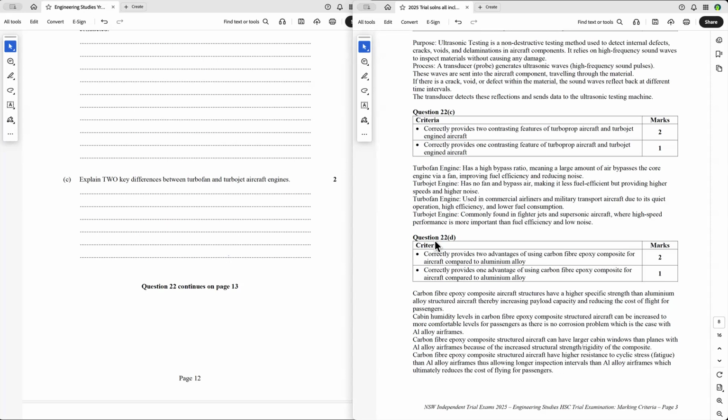And because you've got high wind shear, you've got to have the same momentum, so that with a turbojet, you have to have momentum as mass times velocity. You can't have as much mass, so you've got to have a higher velocity, and it causes a lot of wind shear at the end when it comes out and enters into the still air, and it's very noisy. Whereas a turbofan has a much bigger aperture, and so it can increase the mass, so therefore reduce the velocity, and you've got less wind shear, so they're much quieter than turbojets.